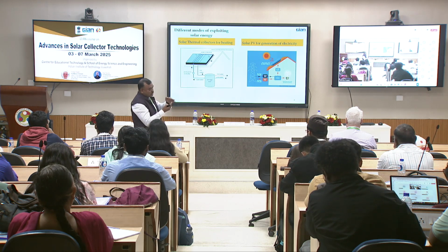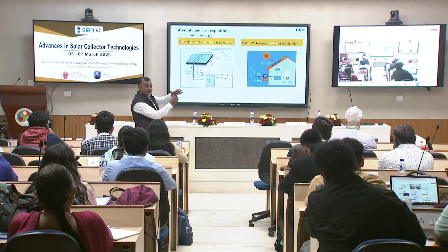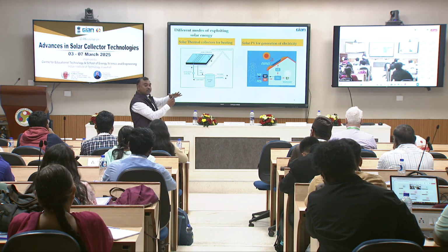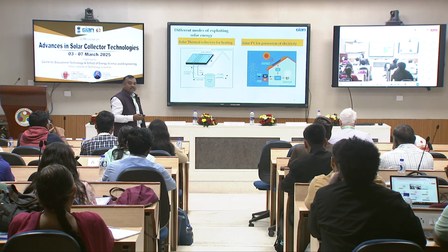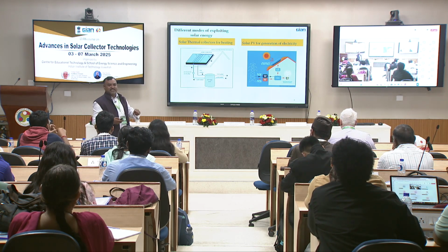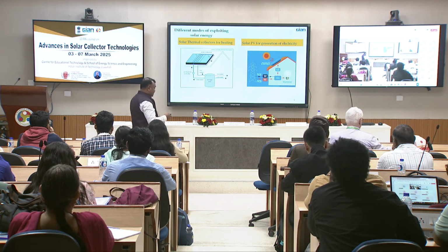Something like pressure bonding is done when we have flat plate collectors and then tubes, then we need to attach them somewhere, we need to apply some kind of material there to fix it. So what could be the thermal resistance offered by this foreign material? Can we remove it? So these are the challenges, and that's how evacuated tube collectors came. What they did was try to reduce the convective heat transfer so that they can maximize the energy conversion, right? So that's how the development happened.